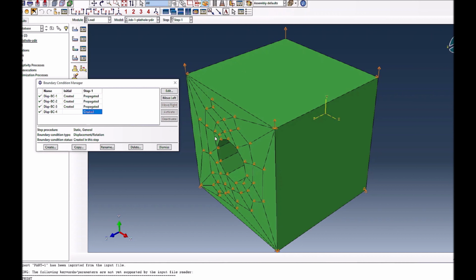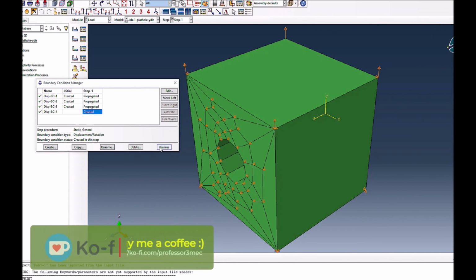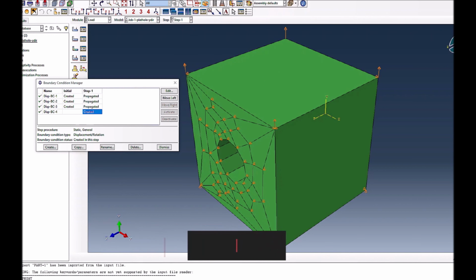So in this model, I think this is the reason why you are having the stress concentration. To get those zero stresses, you might have to increase the volume of the material around this hole, and you have to keep on increasing it until you are far away from the hole, so that the effect of this stress concentration is completely diminished, and that way you will be able to simulate it.